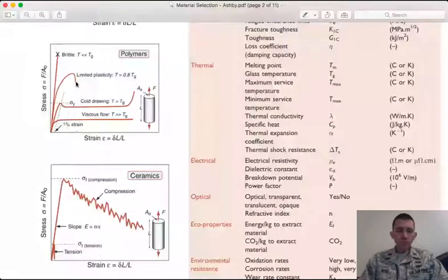And so you can actually generate all of these different stress strain curves from one polymer system just by changing the temperature, right? You see here that you get very brittle failures if your temperature is below the glass transition temperature, right? Which means that you don't have enough energy in the material for those polymer chains to be able to move relative to one another. If I increase the temperature, right, then I switch that condition, and now they do, and so I get very large amounts of deformation.